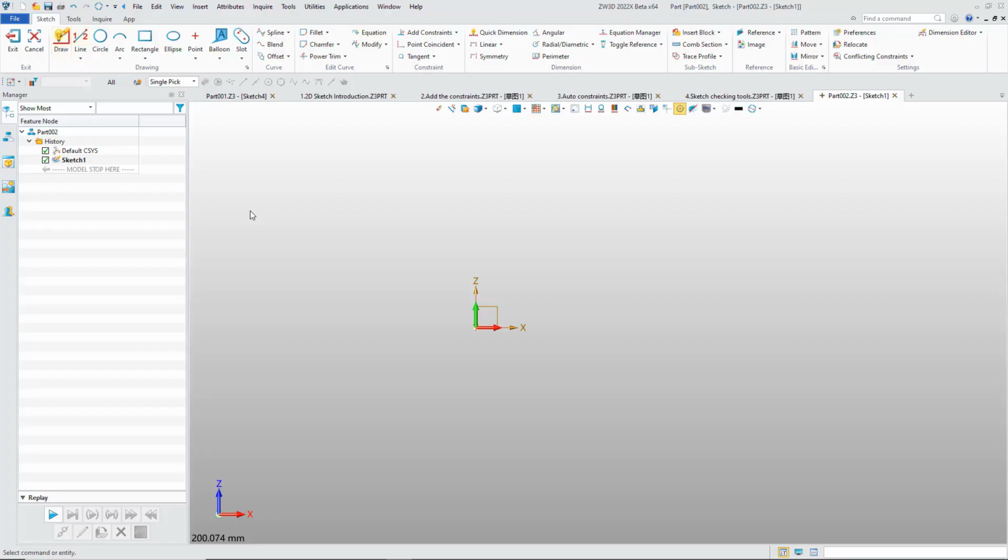You can find the Draw tools from the Sketch ribbon tab. Click it, and if you want to draw the line, press the left mouse to select the 2 points. And if you want to create a semicircle, select the Draw tools, use the left mouse to select the first point, and press Alt to select the second point. After that, loosen Alt and click the second point again. You can create a semicircle.